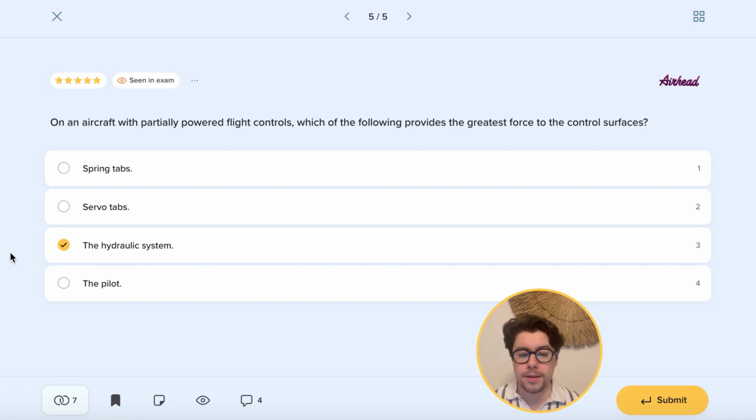And here also remember that there are 3 general types of these controls. Of course, we have the mechanical, using push rods and steel cables, as it is with most GA aircraft. Then we have the partially powered flight controls, which are used in the Boeing aircraft, for example.